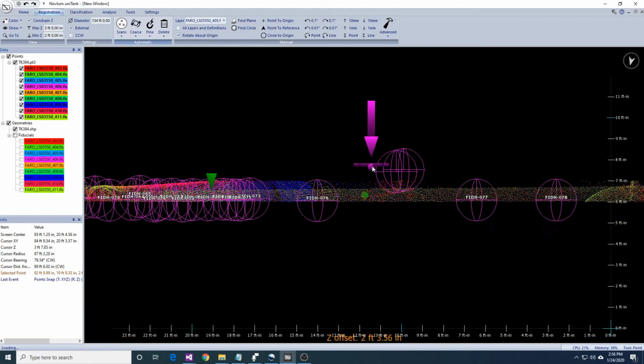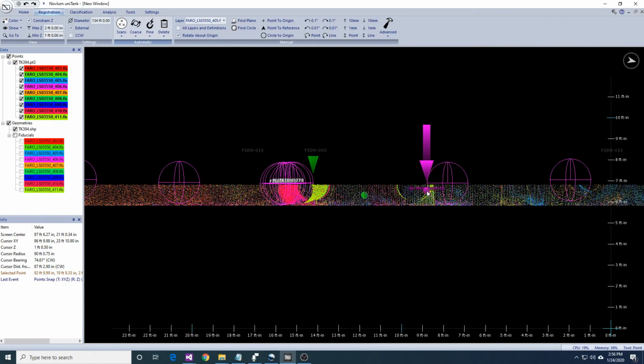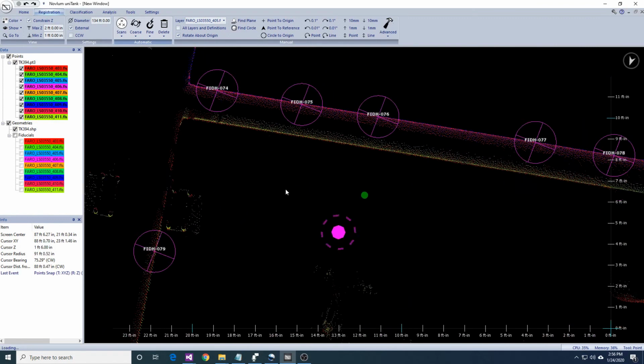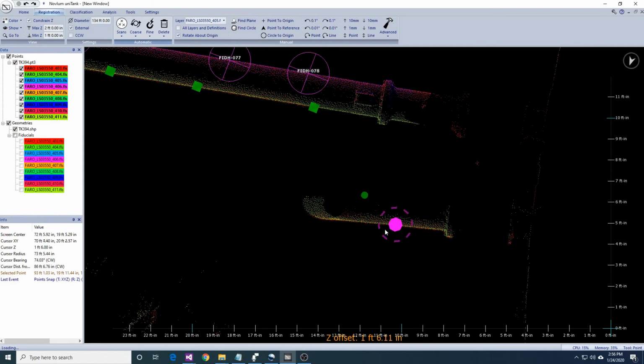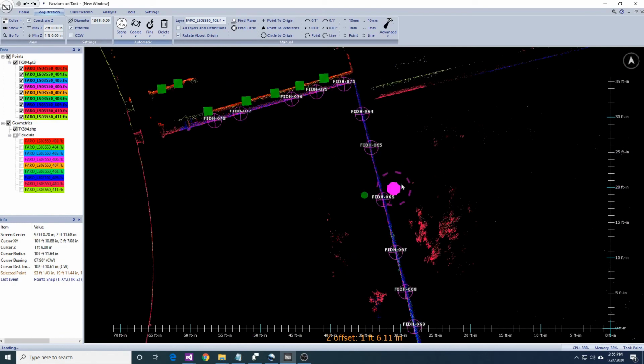You can continue adding fiducials in the model to refine the registration until you are happy with it. Remember, if you run check fiducials, you can see if some fiducials are poor quality. If you find that your model is diverging, this is a good place to see if some of your fiducials are catching on separate surfaces.